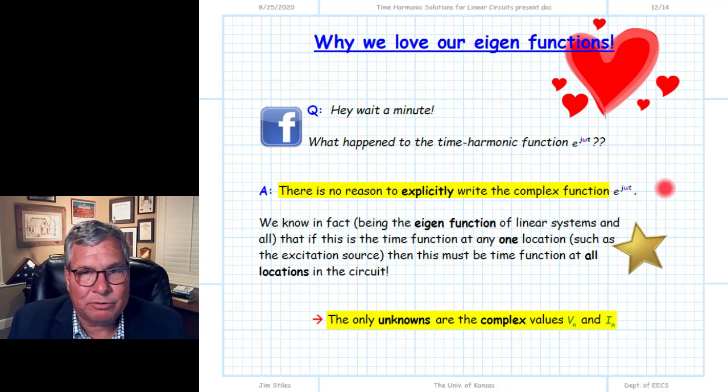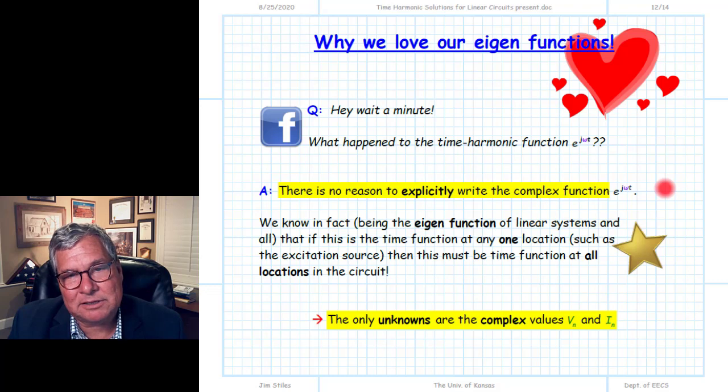We talked about magnitude, relative phase. What about omega? Remember, omega doesn't change from element to element in a circuit. It is the frequency of the original excitation. Once we know it at one place, we know it every place. And that was the great thing about applying complex analysis with Euler's equation, is it really allowed us to separate the unknown phase from the known value of e^{j omega t}, the time varying portion, but varying proportionally to omega, which is a constant across all elements in the circuit.